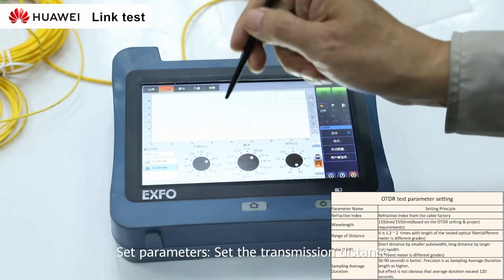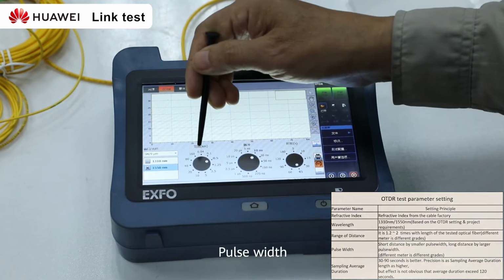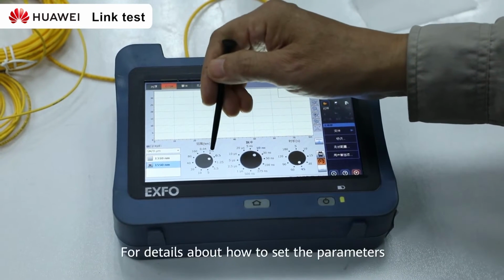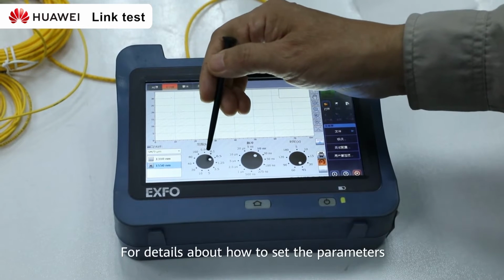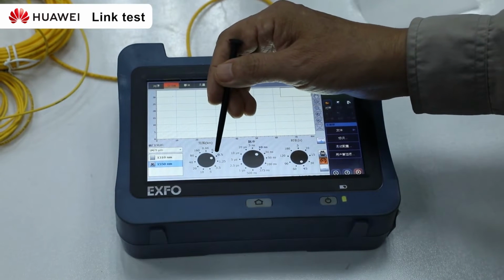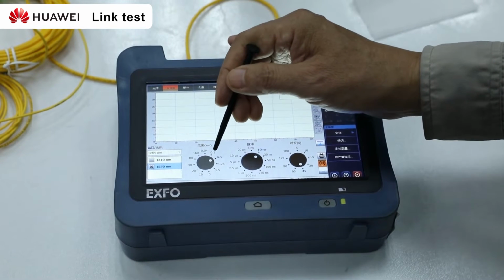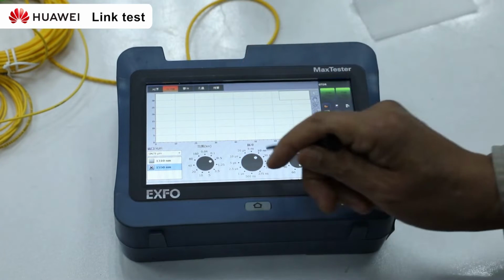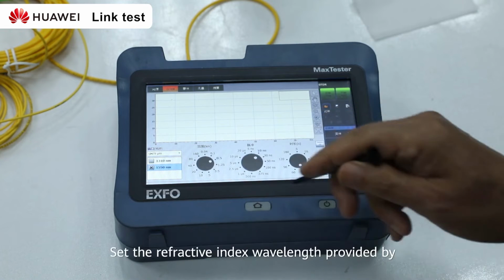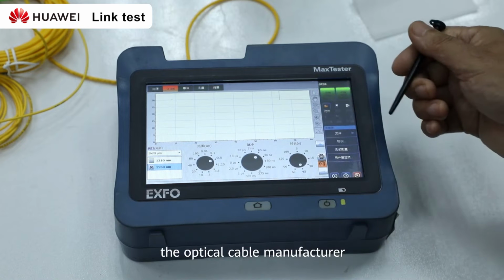Set parameters. Set the transmission distance, pulse width, and average duration. For details about how to set parameters, see the setting principles. Set the refractive index provided by the optical cable manufacturer.